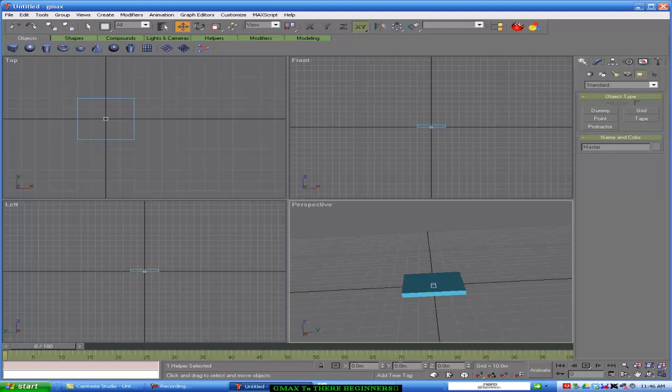Now on the Y-axis, let's say this is a 40-meter deck, so we're going to make about 17 meters. Should put us pretty close to the entrance of that thing. But we're going to put a minus 17. Okay, minus 17 to bring it up to this edge.